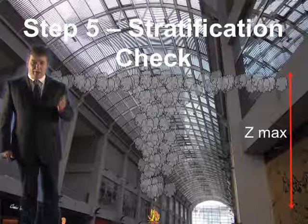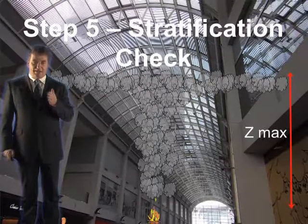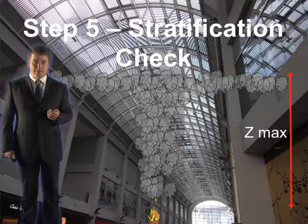Now, we know how much smoke we've got and we know how hot it is. Now we need to start determining how we're going to extract this smoke. Before determining this, you have to consider stratification. And this is covered in step 5, the stratification check. Now, stratification in this atrium is very unlikely. However, for completeness, we will carry it out using this formula.